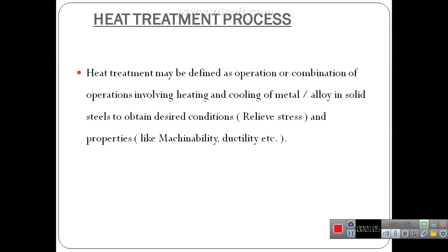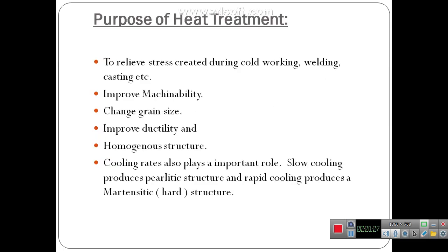The purposes of heat treatment are to relieve the internal stress during cold working, welding, casting, and to improve the machinability of a material. Next, the change in grain size of a material improves the ductility and homogeneous structure of a material. Cooling rate also plays an important role. Slow cooling produces a pearlite structure and rapid cooling produces a martensitic structure.